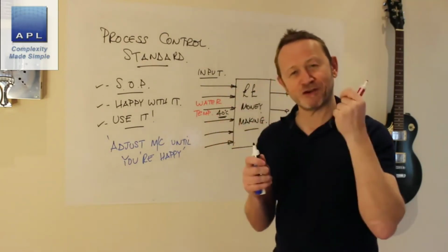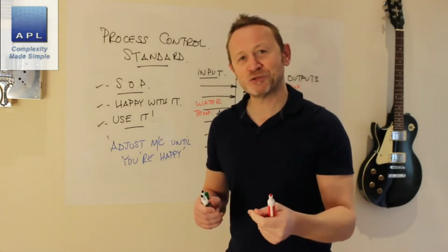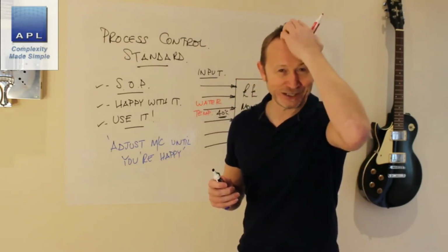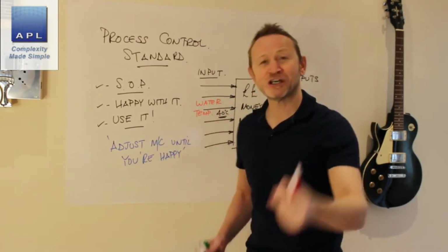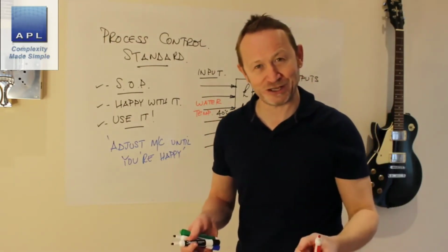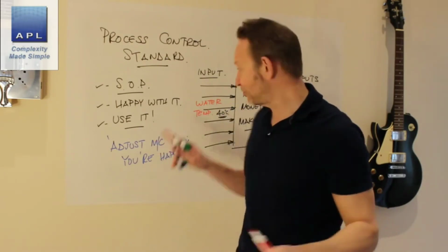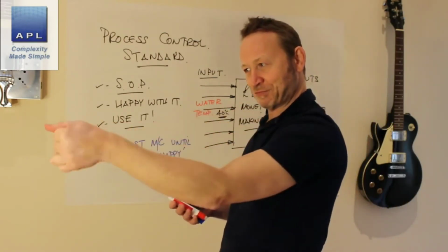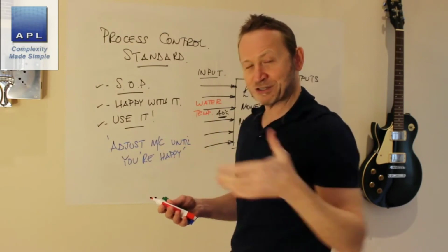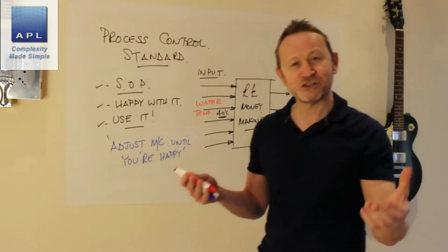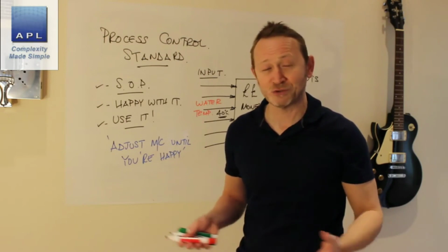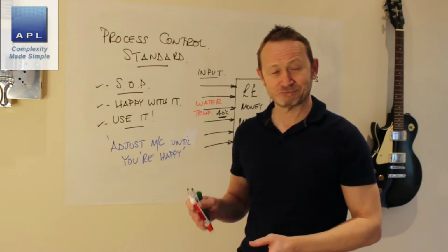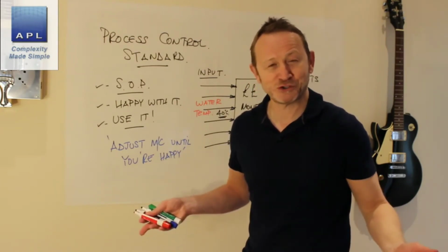Once you've given him the 40 degrees, what do you do next? Well, the next thing you think about is a tolerance. Okay, a tolerance. Now then, folks, the tolerance is a mistake. You don't need a tolerance here. Is it possible for him to dial the setting to 40 degrees, take his hands off, and the setting will stay at 40 degrees? It doesn't move, does it? No. Why does he need a tolerance? He doesn't. Process doesn't move.